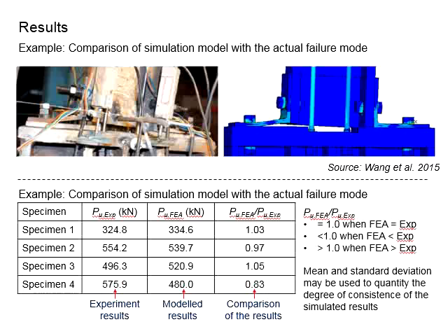And then there will be unique information given by different methods. For example, from the modeling here, you will be able to observe the stress contour, indicating the regions where high stress is concentrated. This will be helpful if you would like to propose improvements for the connections, as the high stress region normally represents the region that has a high chance of causing failure of the connections. Then you may focus your discussions on those.